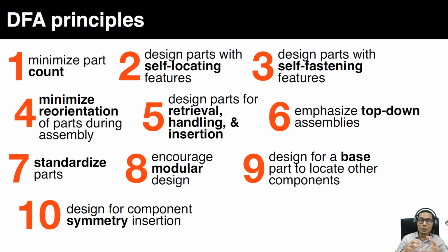Short keywords for the DFA principles, the design for assembly principles. I list out here 10 principles. First, you minimize the part count, meaning that you try to minimize the number of parts. Second, design parts with self-locating features. The third one is design parts with self-fastening features.